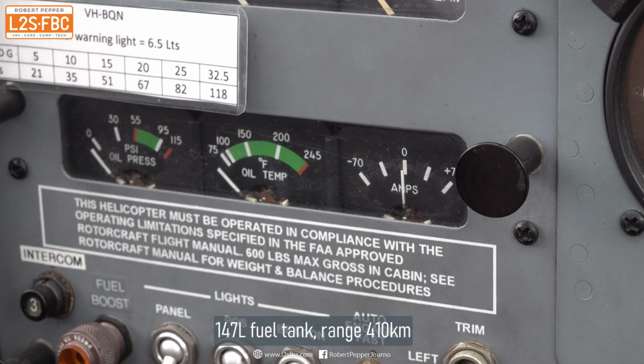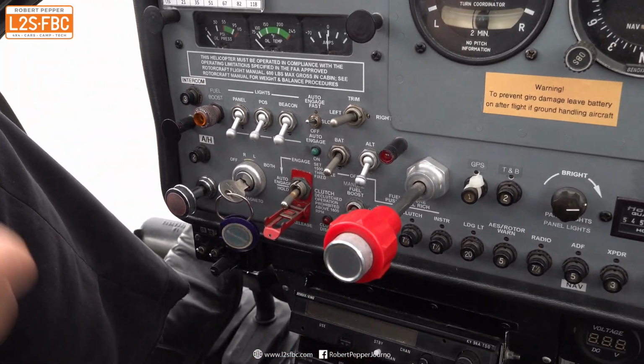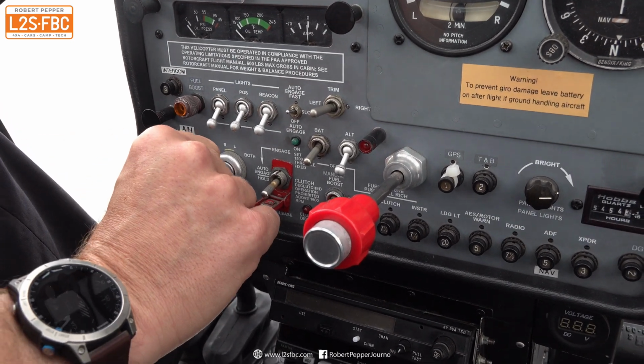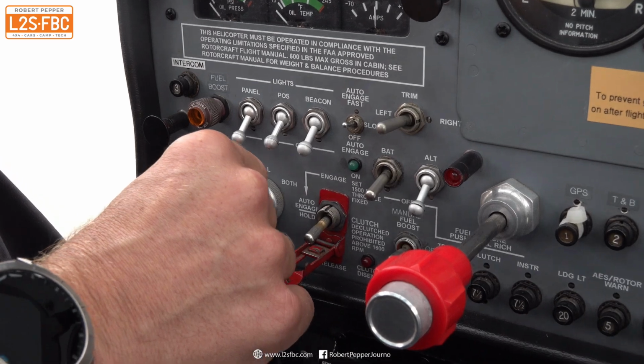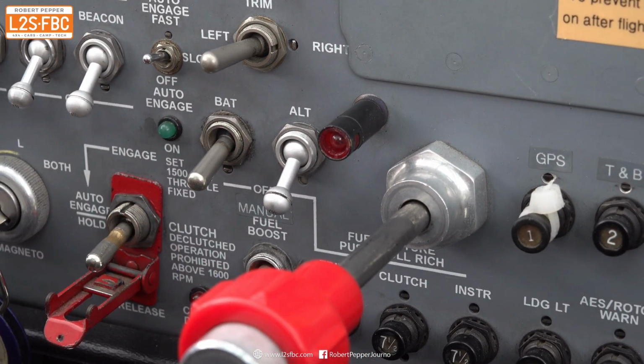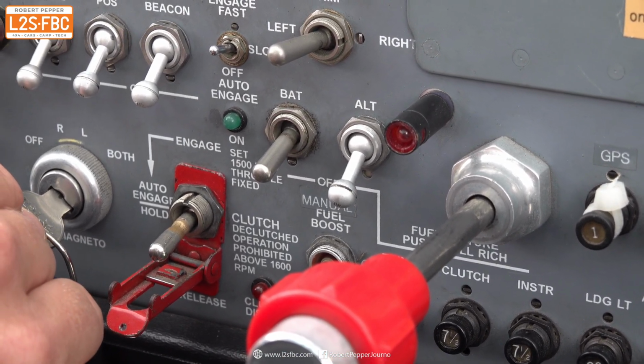Now, starting a machine like this, even though it's a basic helicopter, is not as easy as pushing a button nowadays or just flicking a switch. This is not the starter switch that a lot of students think. To start it, you have to operate a battery. This is actually the magnetos. We have two systems because it's crucial to safety.